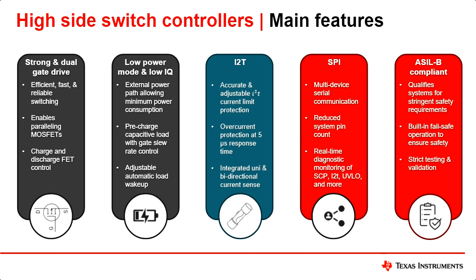The other thing is, with the end equipment mentioned, I2T is something pretty desirable, especially since we experience large transients above max operating current. In most cases, a mechanical fuse is present. So in order for the high side switch controllers to mimic the melting fuse, we manipulate the current over time characteristics of a mechanical fuse to achieve the same result. AKA the I squared T.